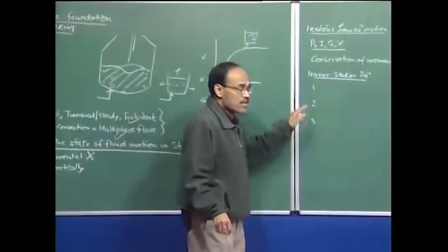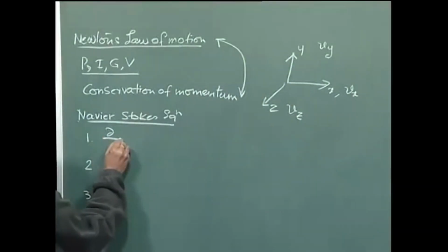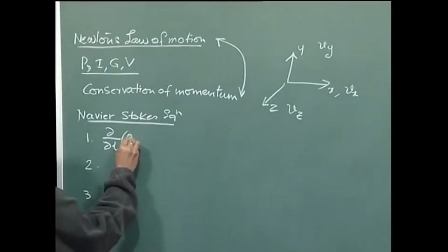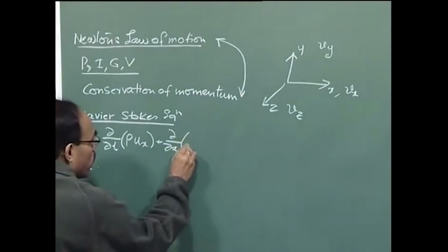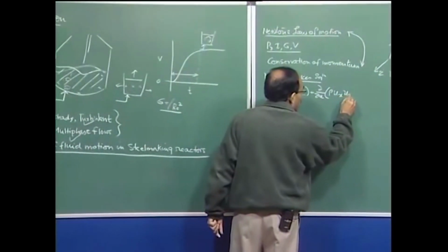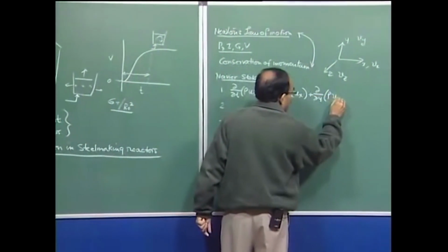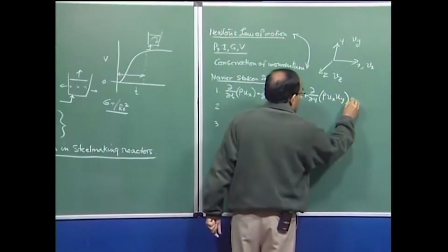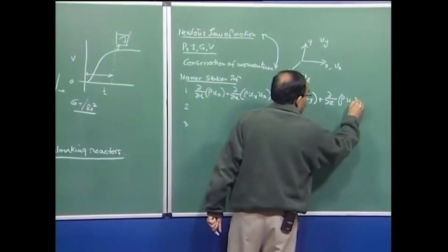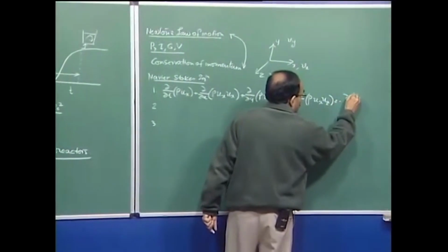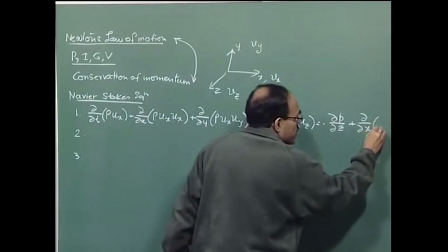And these three equations, as we will see, for example, I can write down the unsteady state equation in a conservative form, three-dimensional. This is the x component of motion that I am writing, and these are the viscous terms.